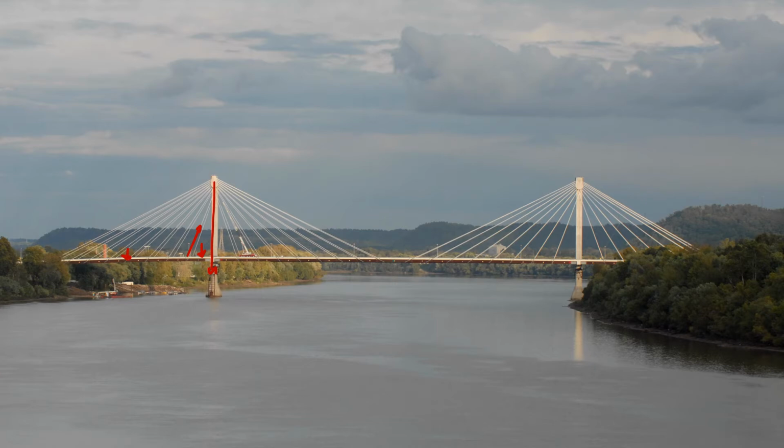Or if you put the truckload over here, it goes up through that cable, down through the tower, and into the foundation. So the difference is that if you lose one of these cables, if you were to lose one of these tendons there, there's an alternative load path for the load to go through to reach the foundations. So this is a more redundant structure. Therefore, it's considered by just about everybody to be a safer structure. And it means that the failure of just one of those tendons will not likely lead to the collapse of the structure. In fact, when they design these cable stay bridges, they design them so that the cables can be removed one at a time in case they need to be replaced.